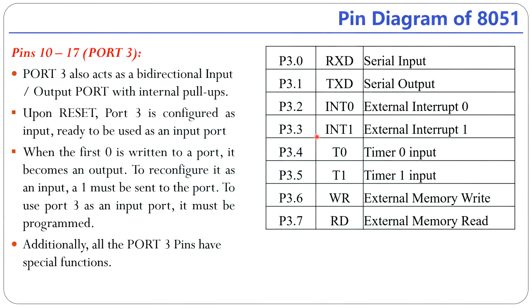P3.3 is INT1, external interrupt 1. P3.4 is T0, the timer 0 input. P3.5 is T1, timer 1 input. P3.6 is WR, the external memory write. P3.7 is RD, external memory read.